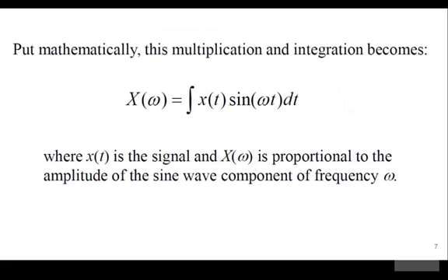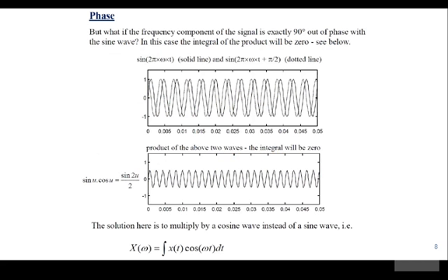So mathematically, we can put this: if we've got a reference signal here, we're going to multiply it by lots of different sine waves of different frequencies, and then we're summing all those up. The only non-zero one is going to be where the frequencies actually match. So we've got a way of determining the frequencies that are present in the signal of interest. And this is just shown in one dimension, or we can extend it to images in 2 dimensions.